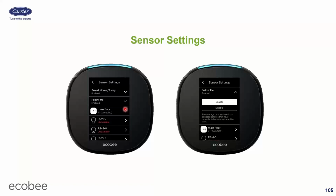Some homeowners will have Eco Plus and some homeowners won't. When you first install the stat, it'll look like this because they won't have the app yet, and obviously it won't be doing anything with the app. But if you're servicing one later on, some of these features like Smart Home Away may no longer be on the stat, and they may be built into the app, and they may have more functionality associated with them. But let's keep it simple and just do it from here. Smart Home Away, like we talked about previously, is where it uses the occupancy sensor, which on the Ecobee 5 is built in right here, or it's built into the remote sensors. It'll use the occupancy sensor to decide if you're home or not home, and it'll switch you between home and away set points accordingly.